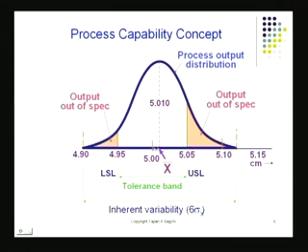And that's going to be my tolerance value. If you supply me products that are in this range, I'll be pretty happy. Of course, I'll be most happy if you supply it right at the target. But I'll accept things that fall within the upper spec limit and the lower spec limit. And this is my tolerance band. This is what the customer conveys to you.